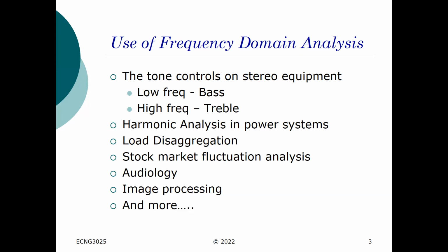Something called load disaggregation, which is a nice signal processing application. This is where you take, for instance, you do a measurement of the power consumption, let's say on a house, and based on the signatures of the various components inside of that current, you can tell, well, okay, the air conditioner was used so much, the refrigerator used so much, and the pump used so much, and that kind of thing.